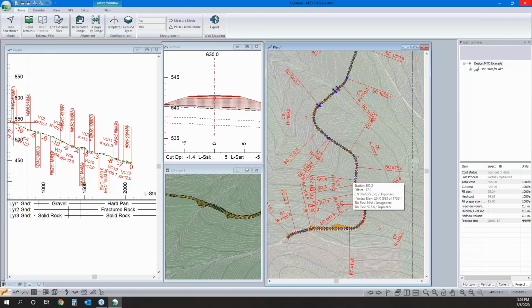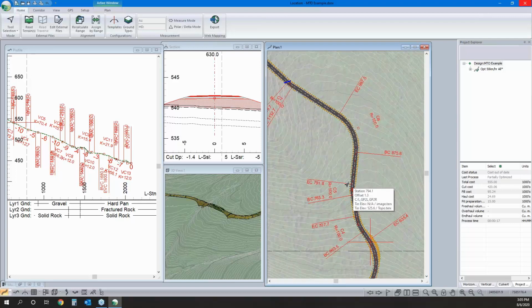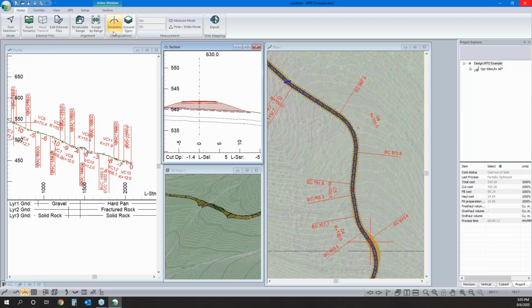Oh, of course, we've taken into account things like stripping. So we're going to assume that we've got an organic rich layer of soil that we want to get rid of before doing our excavation and earthworks to build that subgrade. So that's being accounted for. It's just kind of outside of what I was going to cover, but it's applied in here. So in site prep, we're removing a foot of soil, 0.3 of a meter.